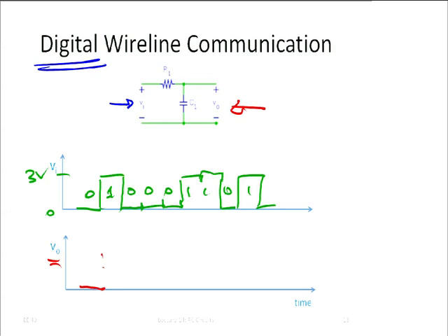That's really what happens. Of course, what parameter would you have to adjust in order to make this look more like a square wave? The red one? Yeah, it is tau. Tau is R1C1. If you make this really, really short, then exactly what we plotted here will still happen, but it will happen really, really fast. So if you make the resistance really small, it goes faster. If you make the capacitance really small, it goes faster.